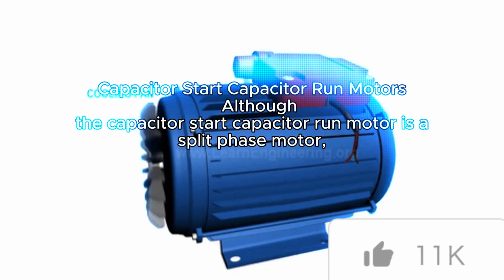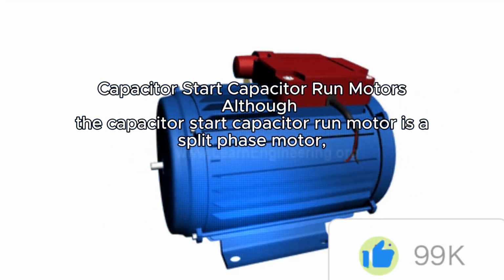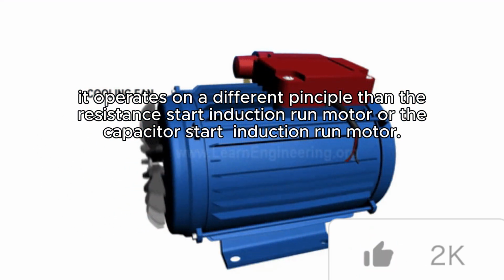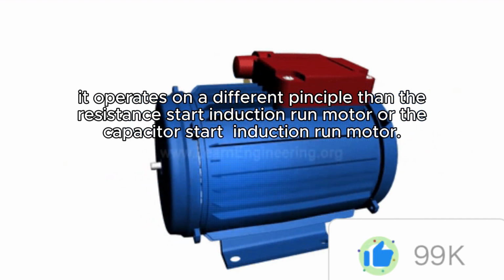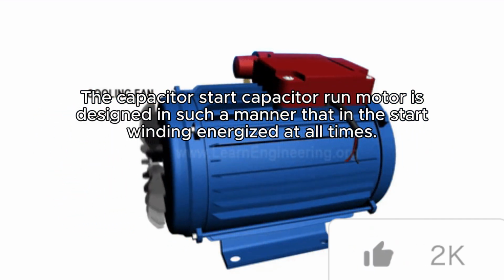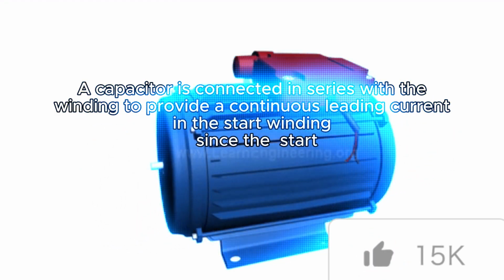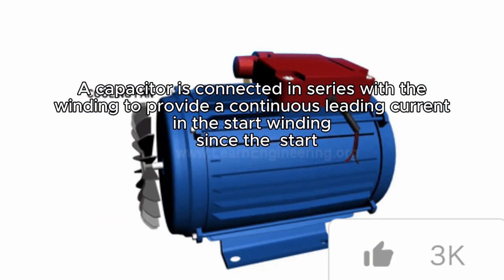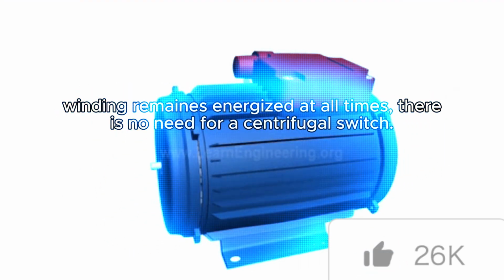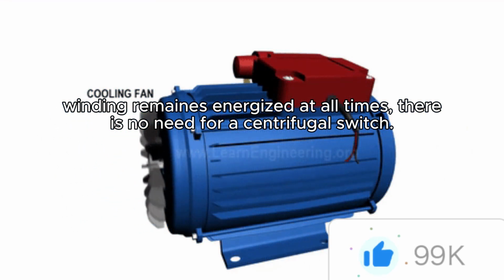Capacitor start capacitor run motor. The capacitor start capacitor run motor is a split-phase motor. It operates on a different principle than the resistance start induction run motor or the capacitor start induction run motor. The capacitor start capacitor run motor is designed in such a manner that the start winding is energized at all times. A capacitor is connected in series with the winding to provide a continuous leading current in the start winding. Since the start winding remains energized at all times, there is no need for a centrifugal switch.